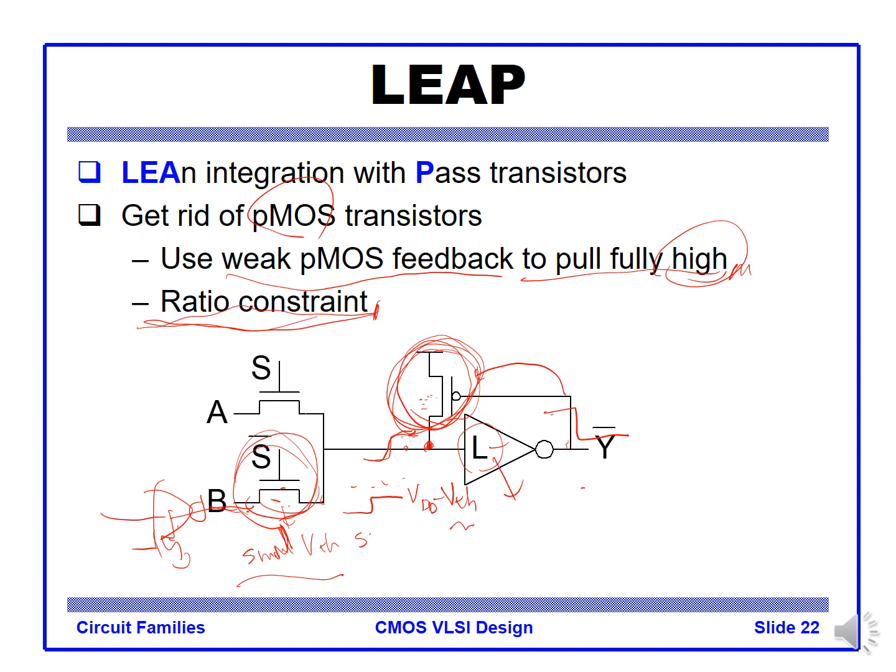And also for the low skew device, the PN ratio needs to be adjusted so that the NMOS is greater, instead of the 2:1 ratio. To make a low skew device, we make the NMOS device larger, so that when the input goes up slightly, this one wins over that PMOS, and the pull down happens faster than a typical 2:1 inverter.